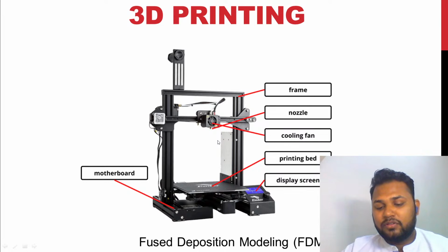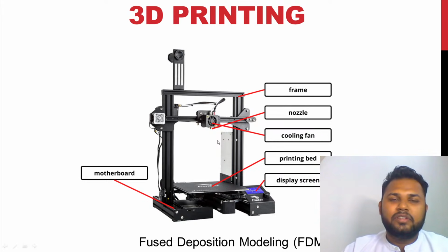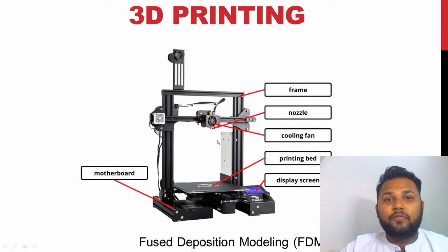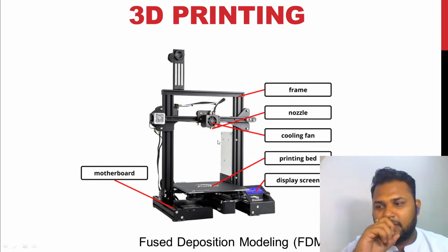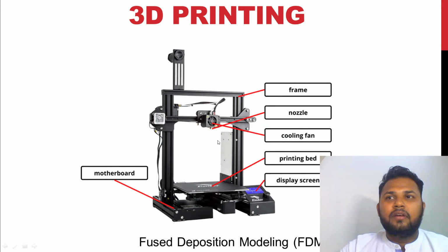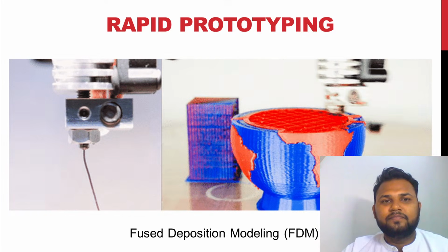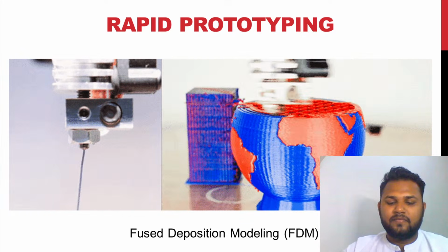And bed temperatures also someone has written. Very nice. Bed temperatures 50 to 60 is okay, but we can also use a cold platform. Like we don't need any temperature rise for PLA material. PLA is such a versatile material. It is also biodegradable. So can anyone tell me what is the full form of PLA?